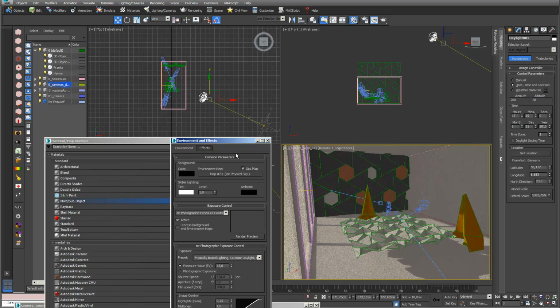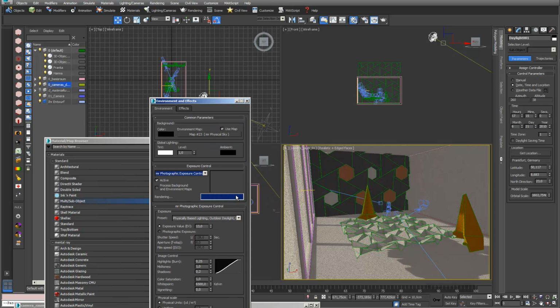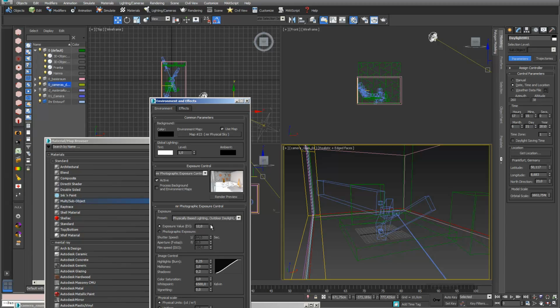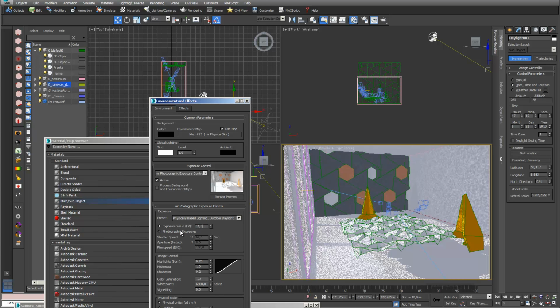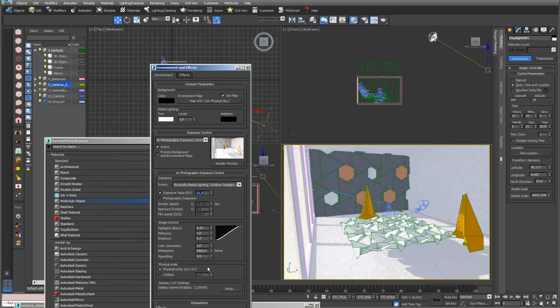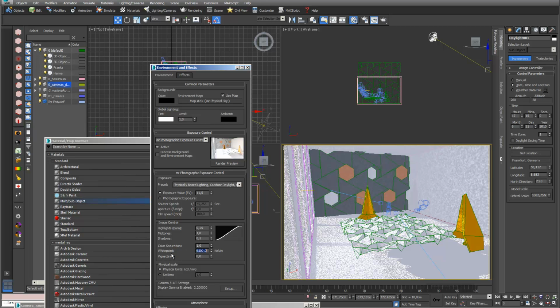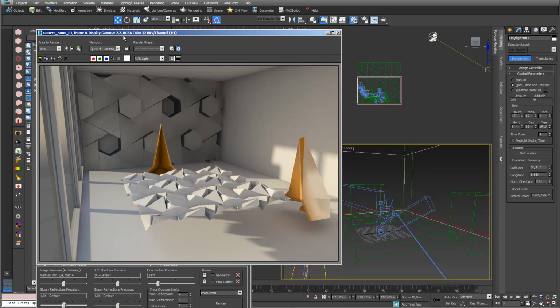This is possibly actually a little bit too bright, so I go into light, environment, exposure control, and here's a little bit like a render preview. If you go into your render preview, then you can go into exposure value and make it brighter. The smaller the number is, the brighter it is actually, and I'll just say 11.5. You can adjust the white point. It's a little bit like with an SLR camera, which is also sometimes really important. I change it to 6500 again, and here I have the feeling it's probably better if I just say exposure value 12.